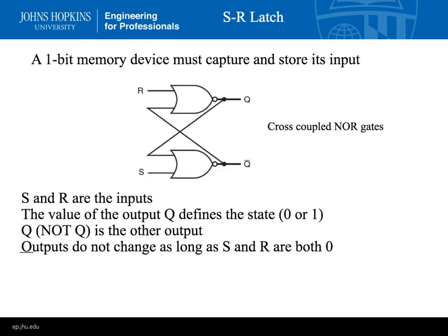So memory is all about storing values and storing sets of ones and zeros. We're going to remember down to individual bits whether bits are on or off. So for each bit, we have to have some way to store whether it's on or off. One of those ways is called an SR latch. The output is Q and not Q. If Q is true, then that's a 1 stored in that bit. And if it's not Q, it's a 0 stored in that bit.